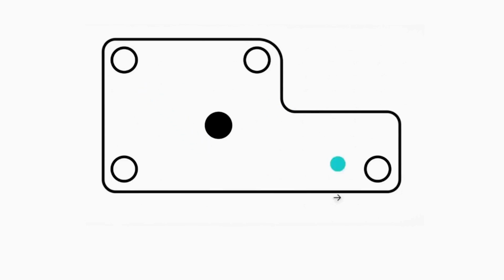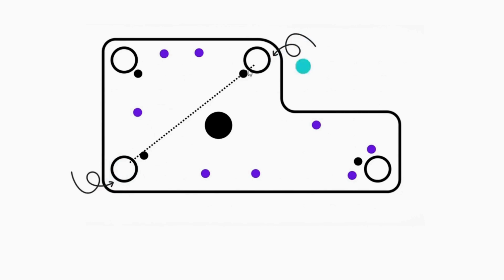If you are not able to give it, then I will tell you what you can do: a two-way locator over here, two-way locator over here, one four-way locator over here, and screw fixation at 60 mm. You can use Christmas clips over here, and I need one doghouse with a locator over here and a doghouse with a locator over here so that it will be diagonally constrained. If I tell you this much, you should be able to do this design. I need not tell you these things. At least I expect this from you.